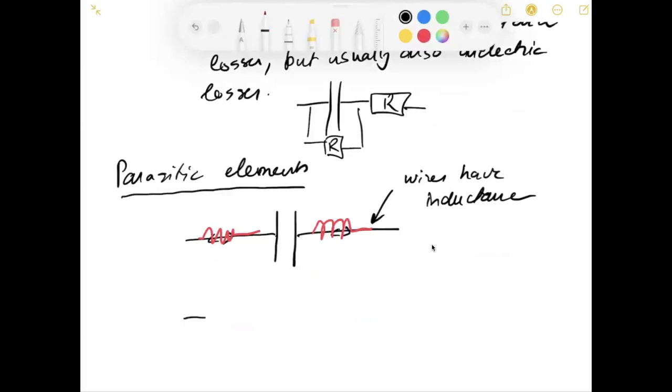Similarly, when you have an inductor and you try to drive a high frequency current through it, there's usually a parasitic coupling between the windings of the solenoid, because these are metal pieces that are placed super close together. In fact, for high inductance, you want your windings to be packed really tight to get a really high inductance in a small form factor.